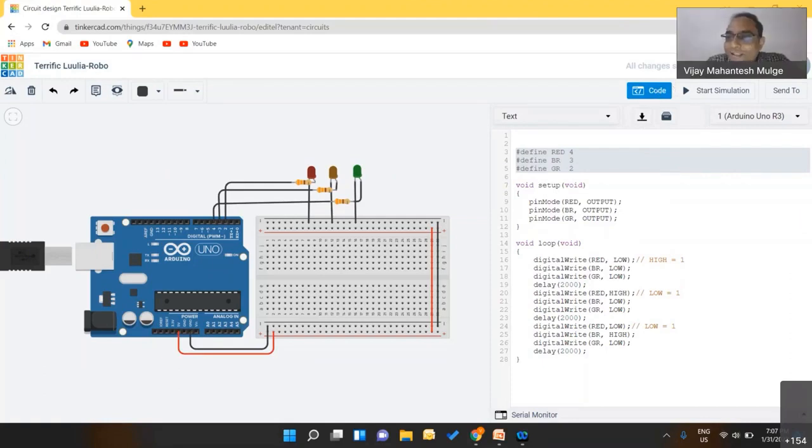Okay, so right, in fact, it is a very, very good question. See, there is going to be a limit to how many LEDs you can possibly add. You have these 14 pins to work with. As far as the digital outputs are concerned, there definitely comes a loading problem, because as you keep adding LEDs, the current keeps getting divided, right? So there is always a limitation, and that is the reason there are always applications that come with some external supply also. We only use the Arduino to control them, and the supply to them will always come from the outside.